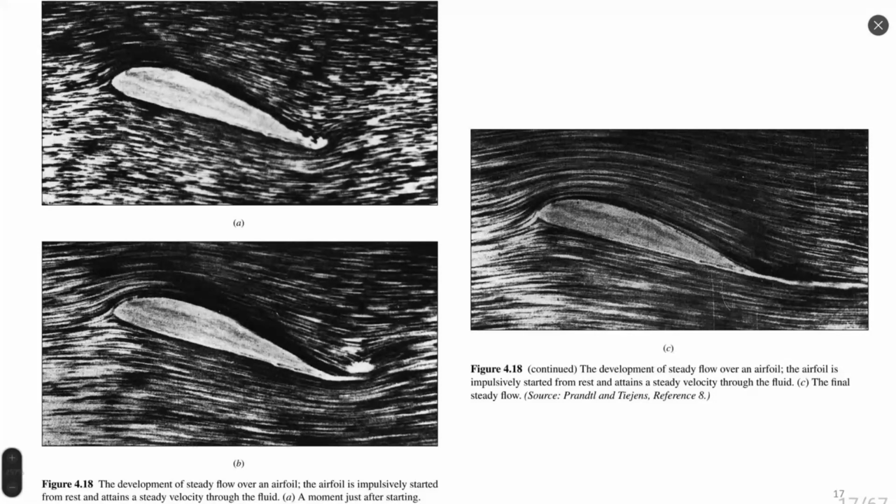This concept of stagnation point on the trailing edge of airfoil is proven experimentally, as you can see here. On each case, for different angles of attack, we can see that flow goes from trailing edge of airfoil. It does not go from any arbitrary point on the top of airfoil. So this flow does not exist.